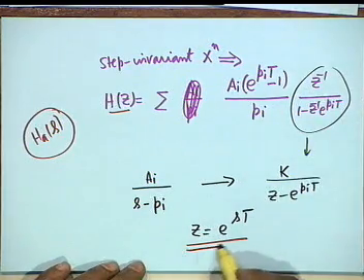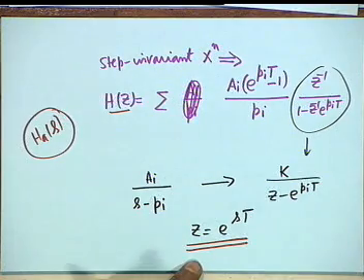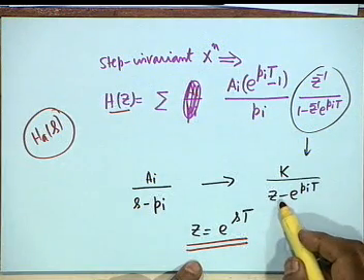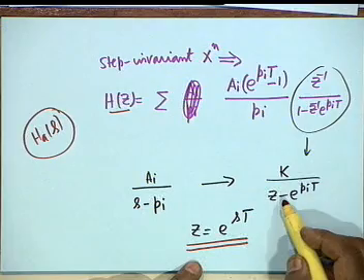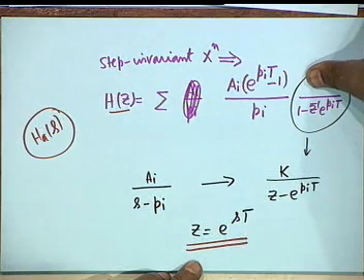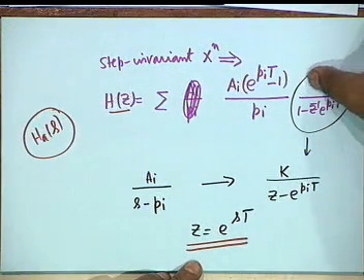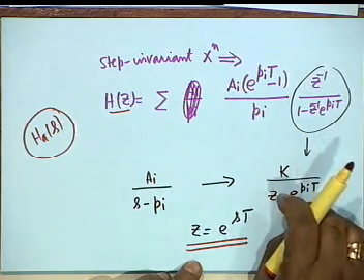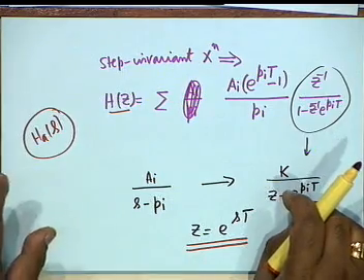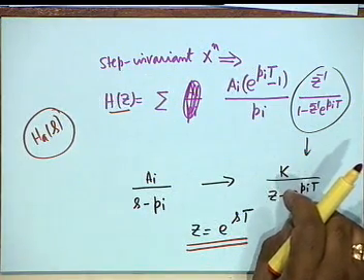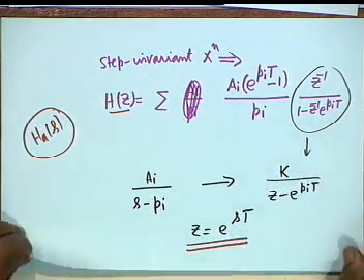In other words, the transformation is the same, but in the step invariant case, there is a 0 at Z equal to infinity. In the former case, there was no 0 at Z equal to infinity. At Z equal to infinity, this term became a constant 1. Do you understand? So step invariant transformation meddles with the zeros of the transfer function, and that is the difference. Just repeat it. Okay, let me.